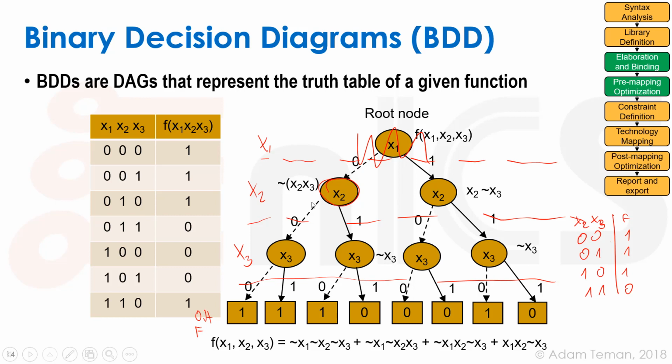So that means that if we start just looking at this node as the tree, we get x2, x3, not. So each one of these nodes in the binary decision diagram represents a complete Boolean function, and we can actually describe many Boolean functions with just one BDD.